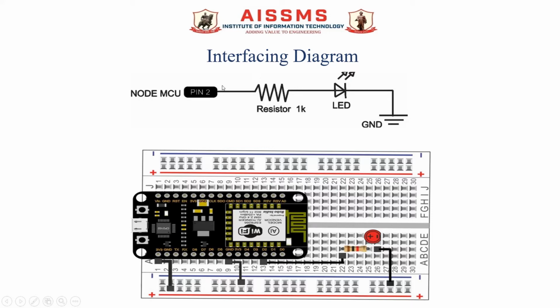This is the interfacing diagram of our experiment. The interfacing diagram is very simple. In this you can observe that the NodeMCU IO pin is connected through this resistor to the LED which we want to control by using the ESP8266 Wi-Fi module. The negative terminal of the LED is grounded and the positive terminal of the LED is connected to the GPIO pin of NodeMCU through this resistor.